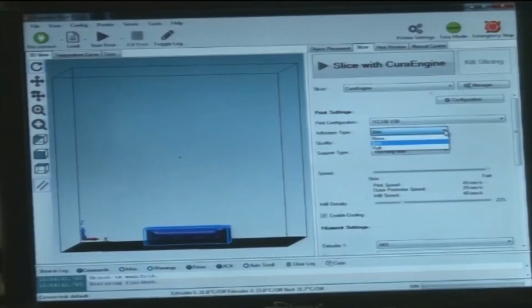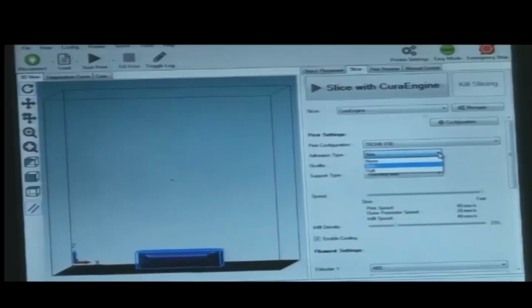What is brim? Brim, as I said, is just at the outskirts of the job. Brims are often used to hold down the edges of your part, which can prevent warping, and it also helps in adhesion with the bed. It is actually known to the manufacturer that the quality of the product varies with using brim or not. In general, the brim command is preferred to reduce the wastage of the material.